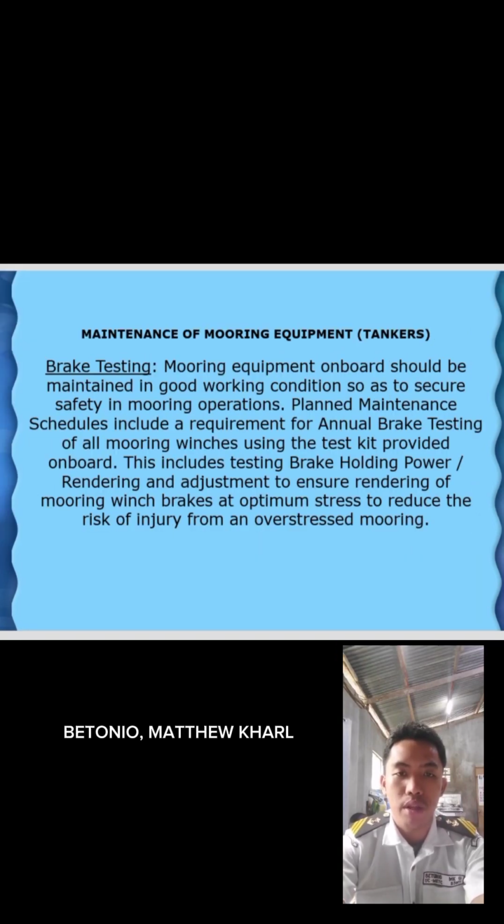Maintenance of mooring equipment. Brake testing. Mooring equipment on board should be maintained in good working condition so as to secure safety in mooring operations. The planned maintenance schedule includes a requirement for annual brake testing of all mooring winches using the test kit provided on board. This includes testing brake holding power, rendering and adjustment to ensure rendering of mooring winch brakes at optimum stress to reduce the risk of injury from an overstressed mooring.